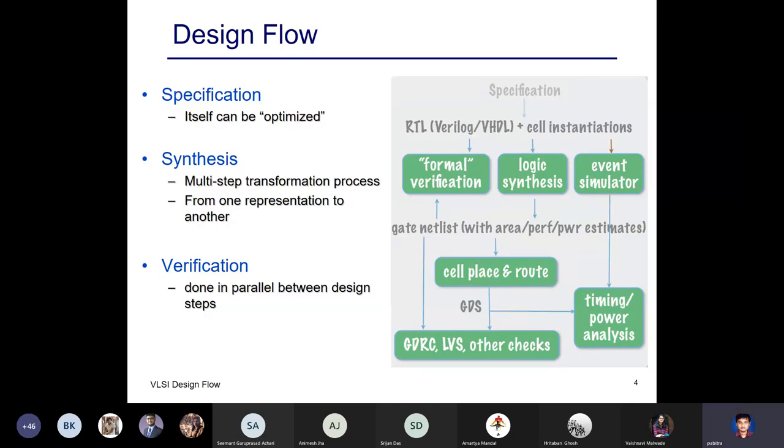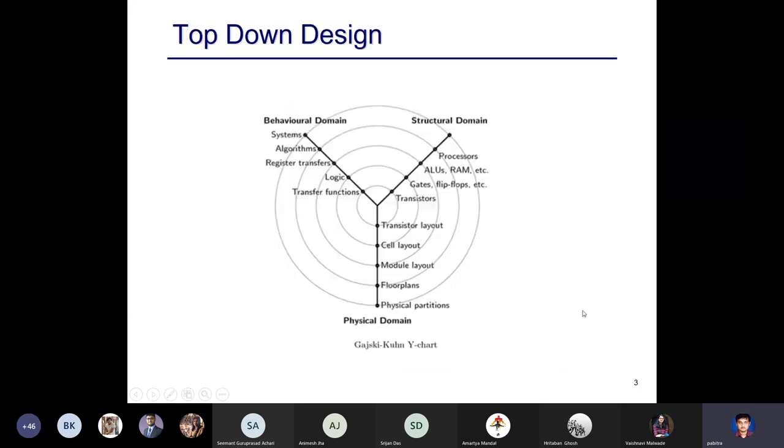But now suppose we are not just happy with simulation, you also want to do synthesis. Now there are two ways of doing it. One possibility is that after this Verilog description is there, you go through further down levels: transistor layout, cell layout. As you go inside, these are called back-end EDA, and outside you have the front-end EDA.